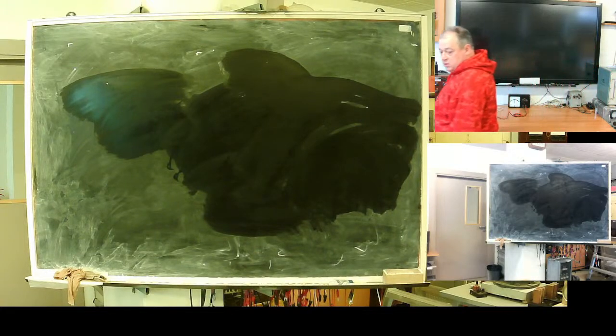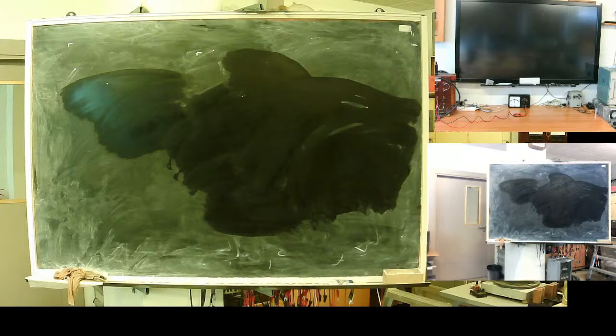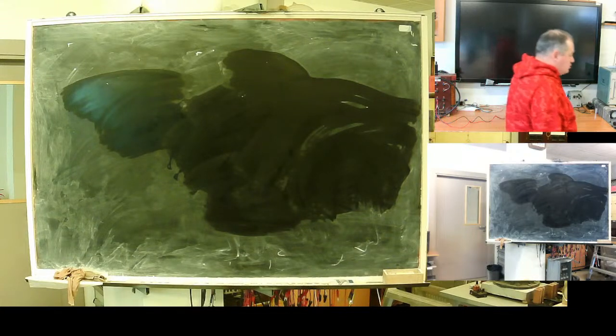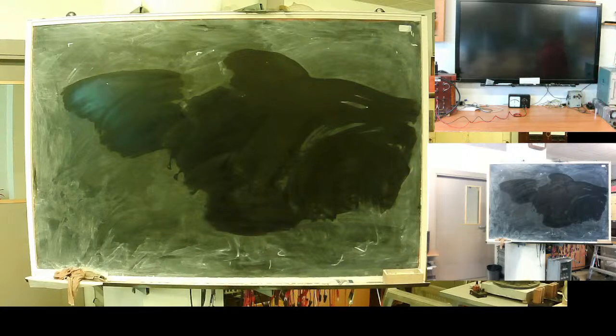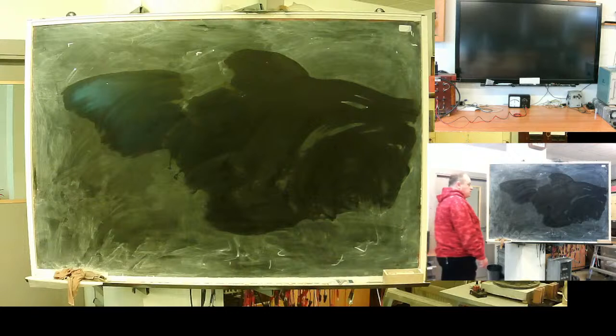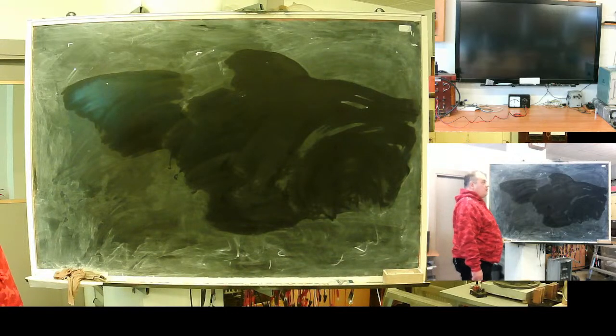We cannot use this technique directly if we account for arc resistance, because an arc is non-linear. If we need to account for it, we are forced to account for non-linearity of the magnetic circuit and so on.